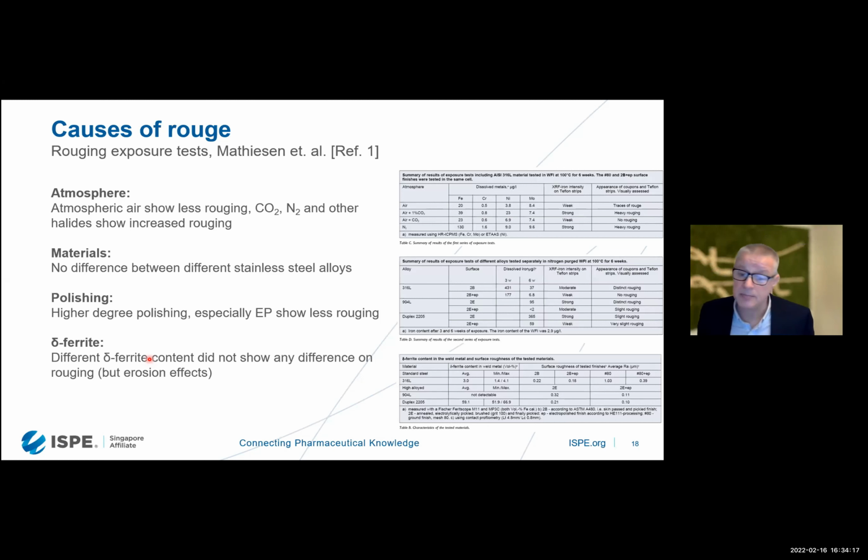And in a pump, you have an impeller. On the tip of the impeller, it could be very, very high velocity. And with this very high velocity, there are risks that small parts from the impeller tip could be eroded away. And when these are eroded away, you get a fresh surface that is not passivated.